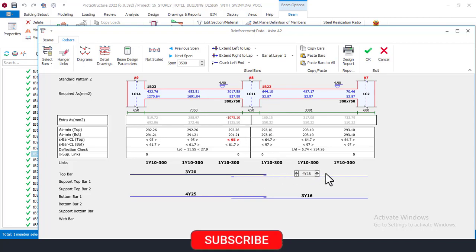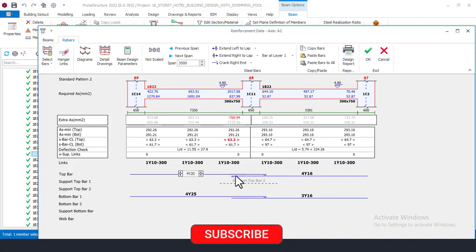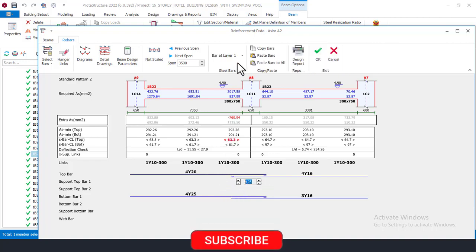That's okay right now on this other span. Then here, come here right now. Here it's still failing. Increase to 4Y20, and then come here, add bar. The same way with the other one. Decrease to Y20 and increase bar size here.